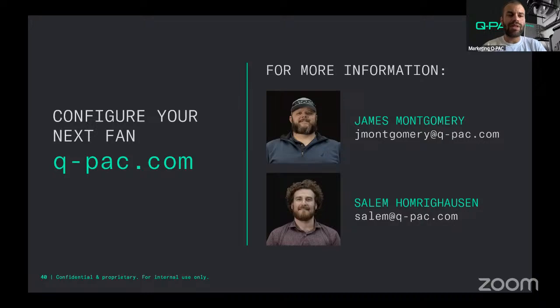Quickly, to circle back to a point from a few minutes ago, you mentioned the dampers at the beginning of that question. Salem mentioned that if you can run for 10 minutes and it's not an issue, you likely don't need a damper. When and if you ever need to replace an ECM plug fan, it truly is those plug and play Molex connectors as well as 8 bolts typically. I think a couple designs have a few more bolts, but 8 is our standard.